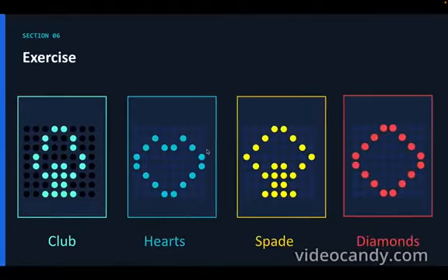So you see, that's how an LED matrix interface works. That's how we load the data. That's how we decide on how many loops we need, what refresh rate, and how long each character is displayed.